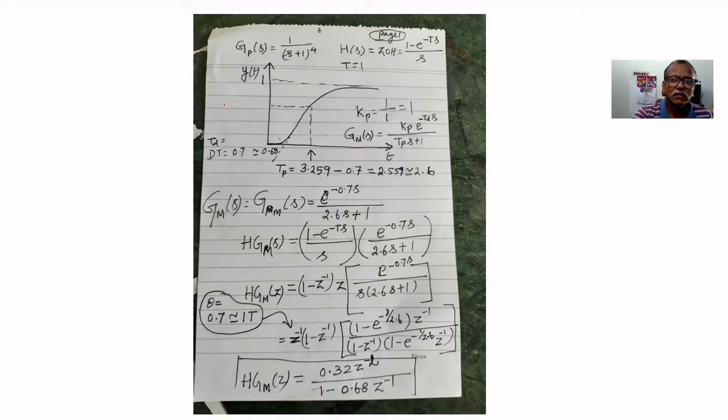First, we want to simulate a higher order system, a fourth order system, that is 1 by (s plus 1) to the power 4. This is very important because no system in the world is first order. Even if it is higher order, its order will be increased because of other components in the loop.